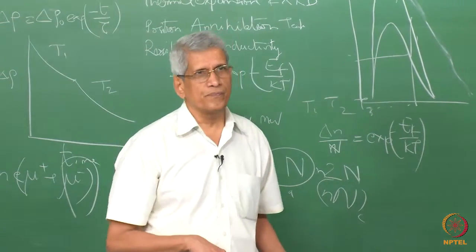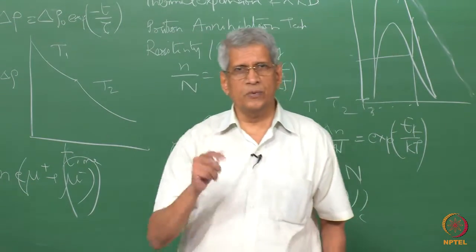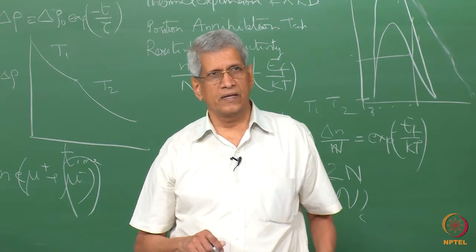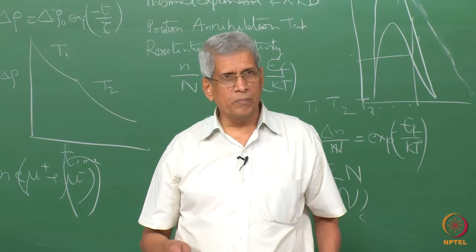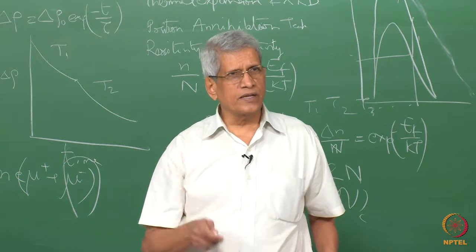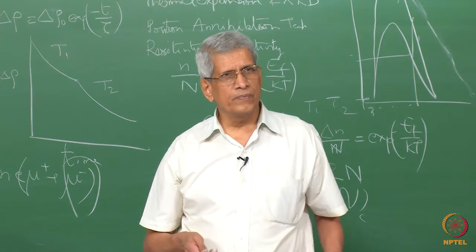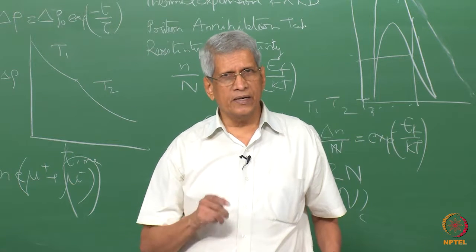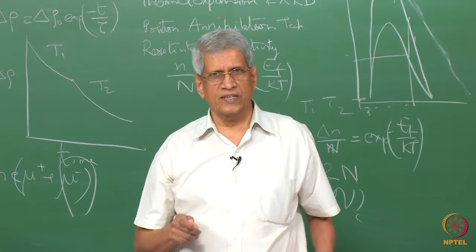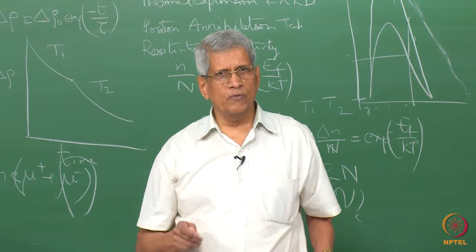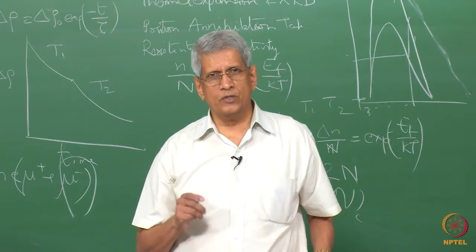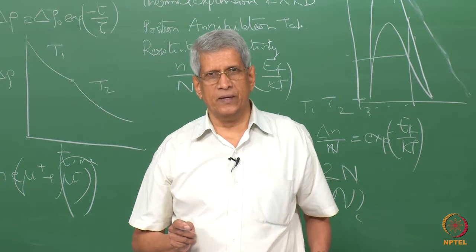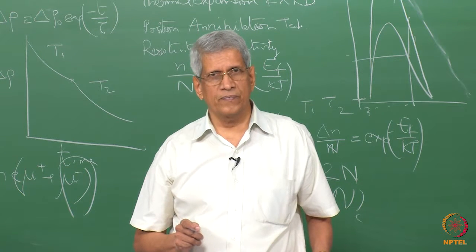Suppose we look at the conductivity at very low temperature, then what will happen? At low temperatures, the Schottky defects are going to be very small. Then the impurity concentration is the only one which is going to decide how much the cation vacancy is going to be in the material, correct?